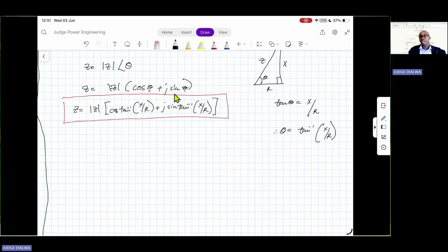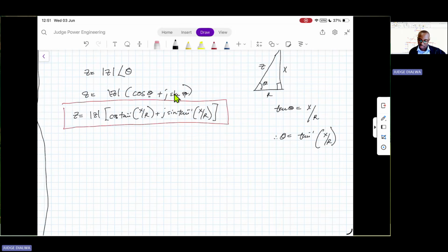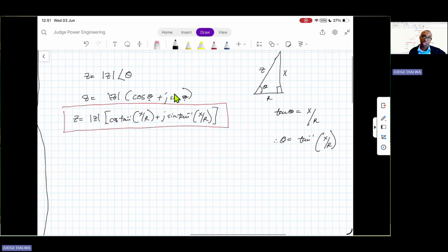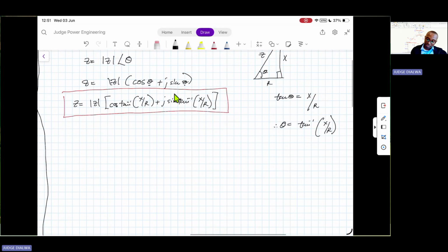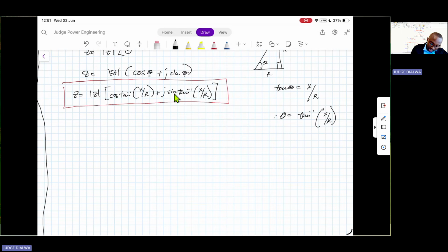So for us to be able to directly compare them, we need to have them at a common base. Since we'll be confirming these calculations using ETAP, which normally uses a base of 100 MVA in computing short circuits, our new short circuit MVA will then be 100 MVA. So this will be our new base.